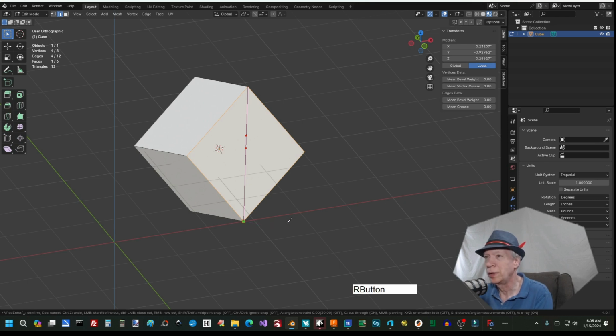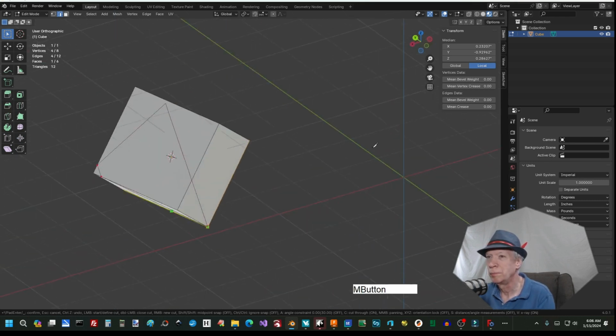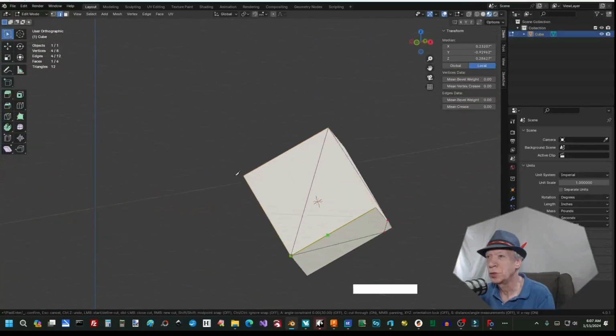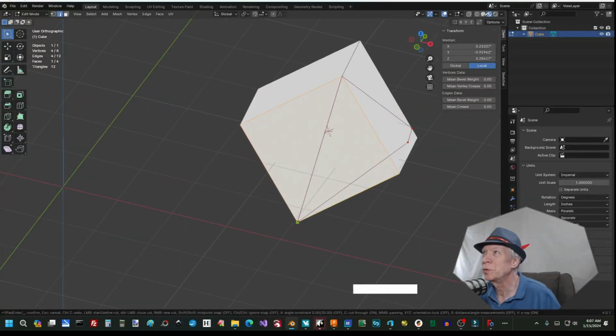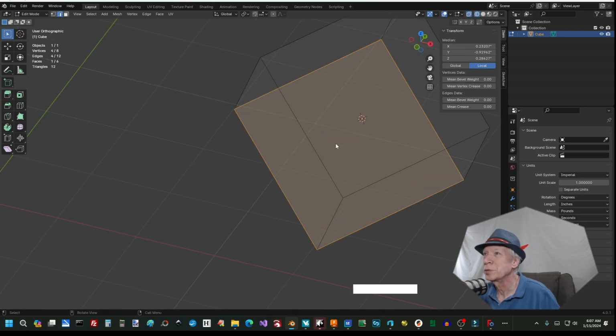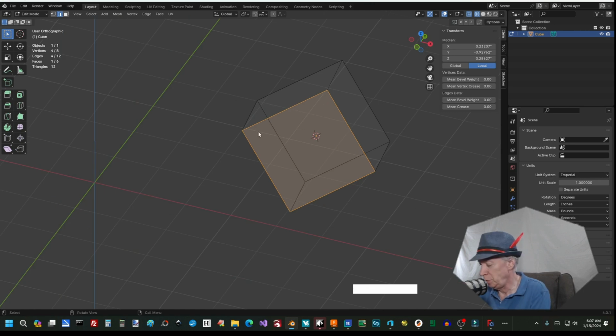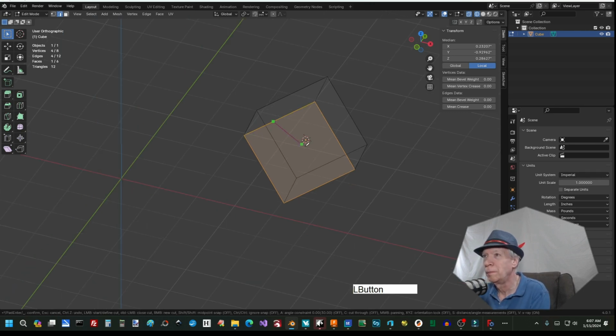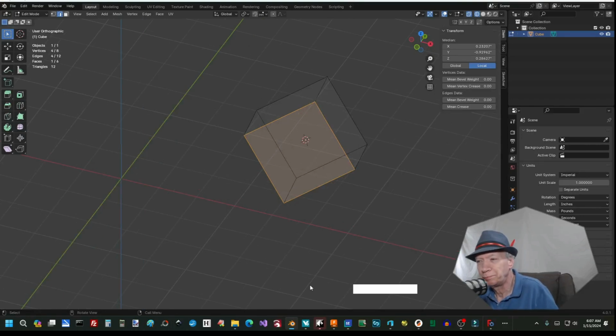And then you can hit right click, and that should have cut through the whole object. Most of them work when the object is opaque, that you're cutting on the sides. If you're in X-ray vision, oops, we got to drop our knife. If you're in the X-ray vision, then what you do with the knife actually cuts all the way through. But not everybody does that.